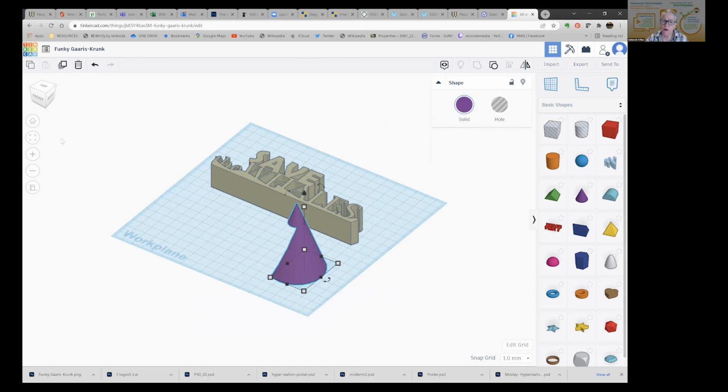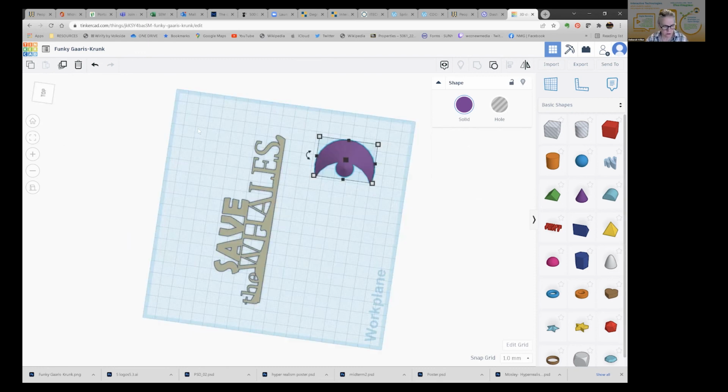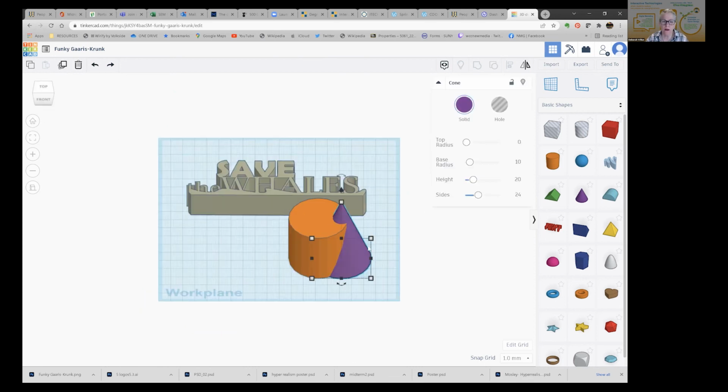So just remember, when you do that, let's go back as it was. Again, reset. Here's my, now I'll do it the other way. I'll highlight these two, just highlight this one. And what you're saying, this is it. In here, it's called a hole, but in 3D, we call it a boolean. And we're going to cut that.